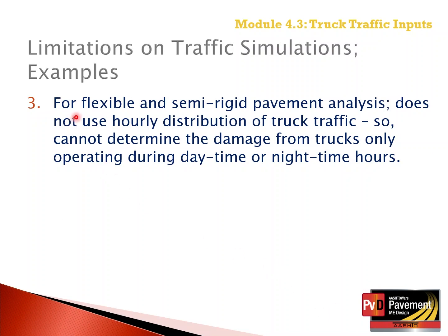The third, for flexible and semi-rigid flexible pavement analysis, does not use the hourly distribution of truck traffic. So we cannot determine the damage from trucks only operating during portions of the daytime and or nighttime hours. In other words, the time of the day is assumed to have an equal percentage of trucks for flexible and semi-rigid pavement analysis.